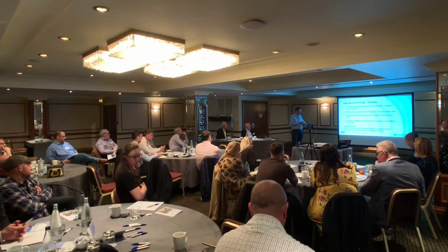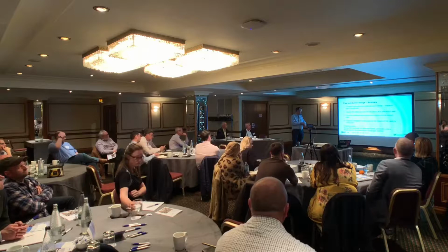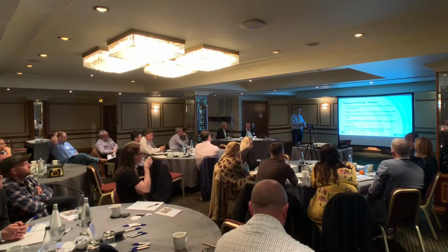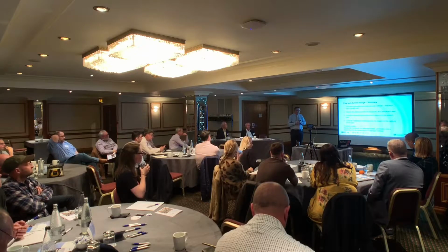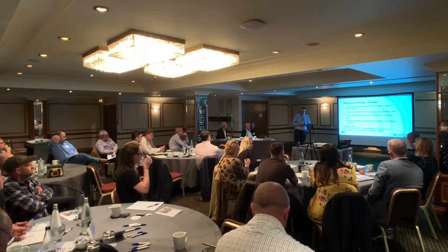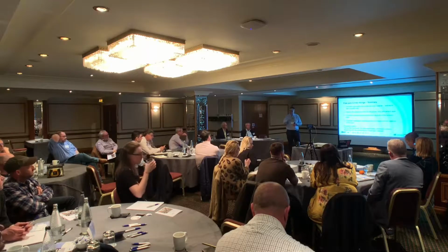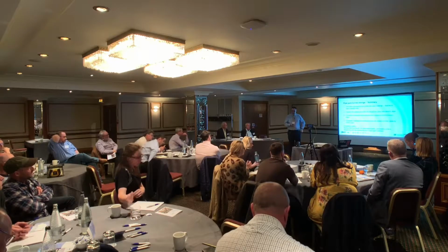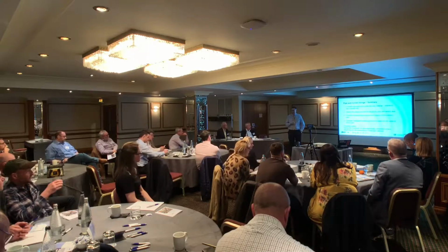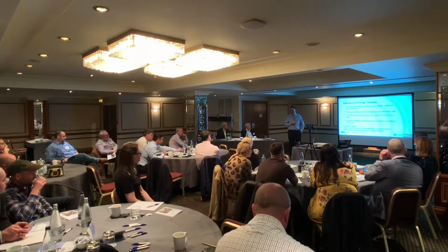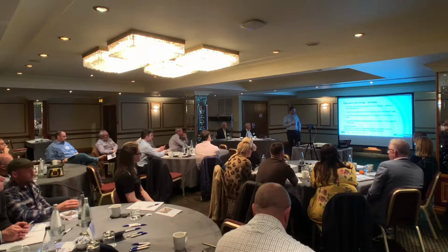So you need to really advise the contractor on estimated jacking loads when you're looking at the temporary case, particularly where you're going to depend on interjack stations. Now I'm going to be talking a little bit later about the backwall design and how those loads are derived, or how they're looked at in the temporary case with regard to face load and friction and things like that. It's important to note that